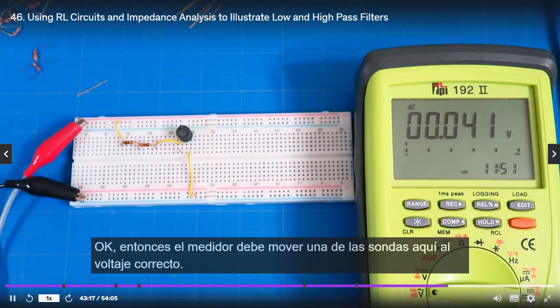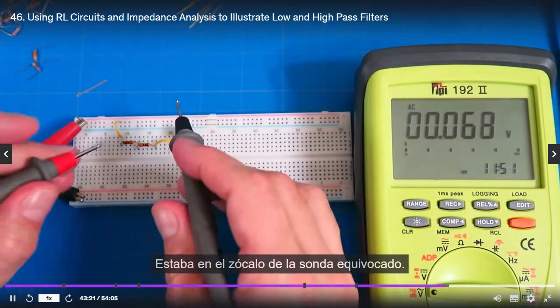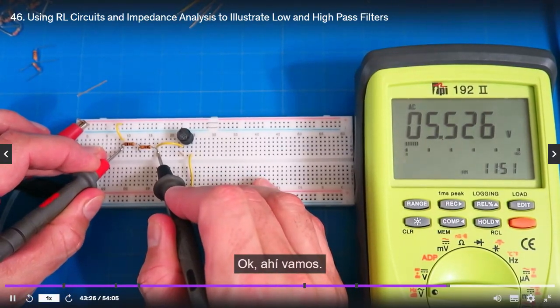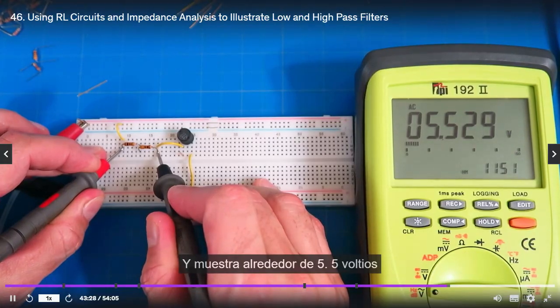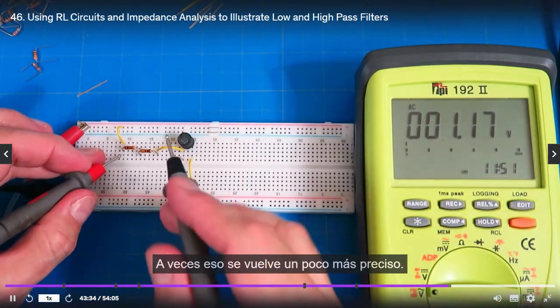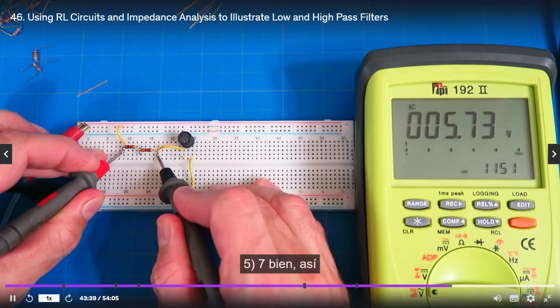Oh, okay, so on the meter we have to move one of the probes to the voltage socket. It was in the wrong probe socket. Okay, there we go. And it's showing about 5.5 volts. Let me change the range. Sometimes that gets a little more accurate. 5.7.